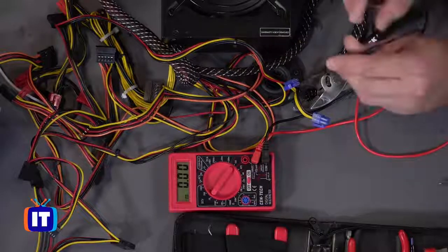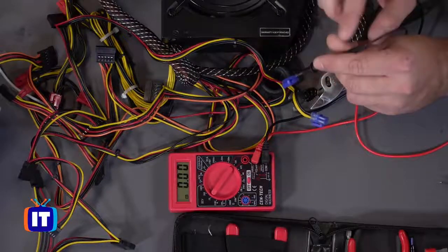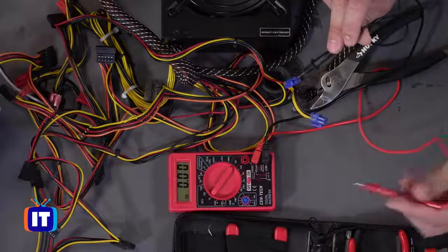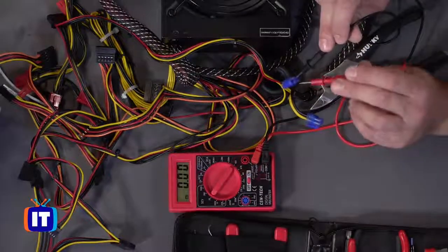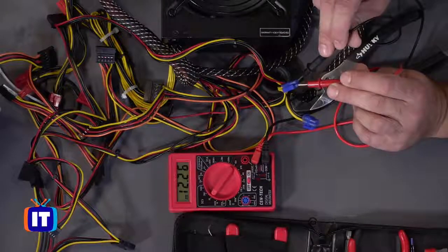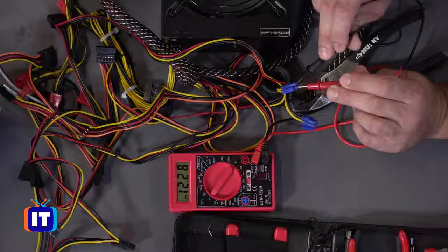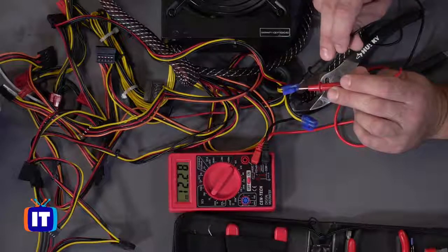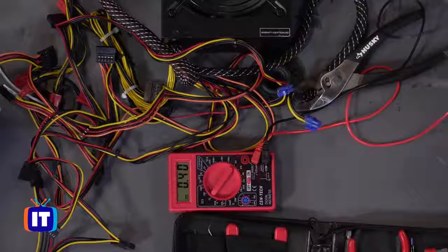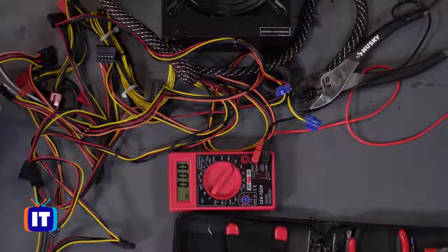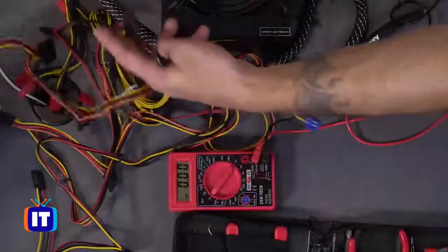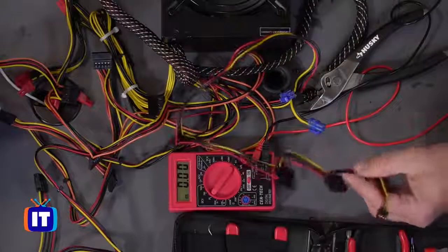So I'll touch the negative probe here to the negative side, and then we'll touch this to the hot wire, and you'll notice that the multimeter is letting us know that it is in the 12 volt range. So what I can see right here is that it's within its tolerances. Keep in mind that it might not be exact, and if it was just a little bit under, that might cause a problem. But if you're a little bit over, remember the device can only pull the amount of power that it's capable of pulling. Now, we could go a little bit farther than this, and I could pull over one of these Molex connectors here, and we can show you one of the other voltages.